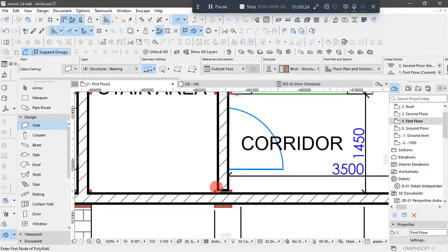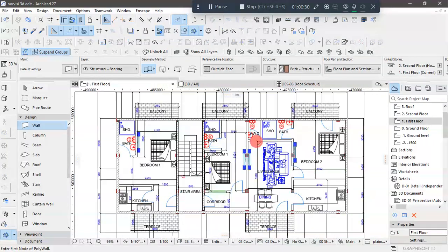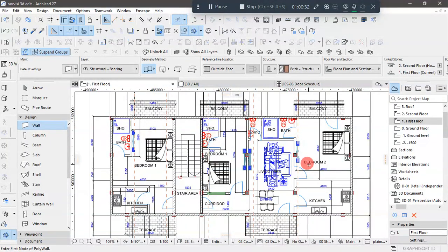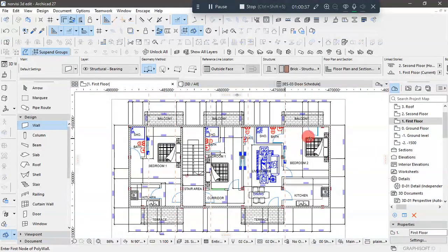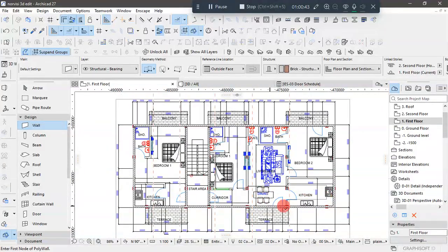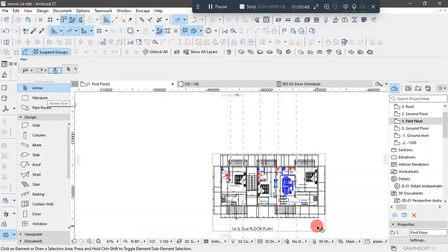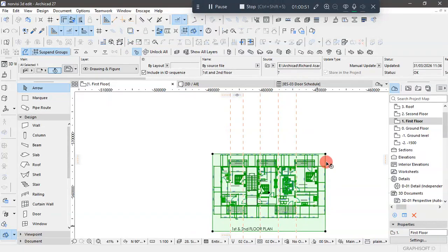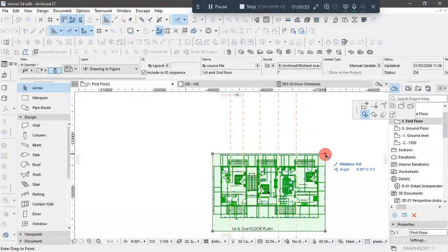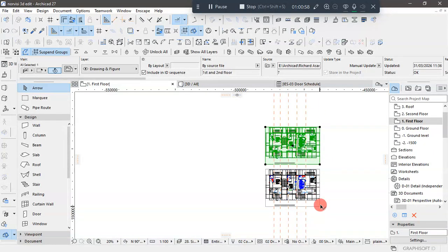But then I think you notice that some of the columns move all the way up. Yes, so we'll have to consider that too. Now this is an internal wall, it will be hidden. I don't want us to concern ourselves with things that won't actually show. Before I continue, let me unlock this and then move a copy up like we did, holding control, then I come back and then unlock it again.